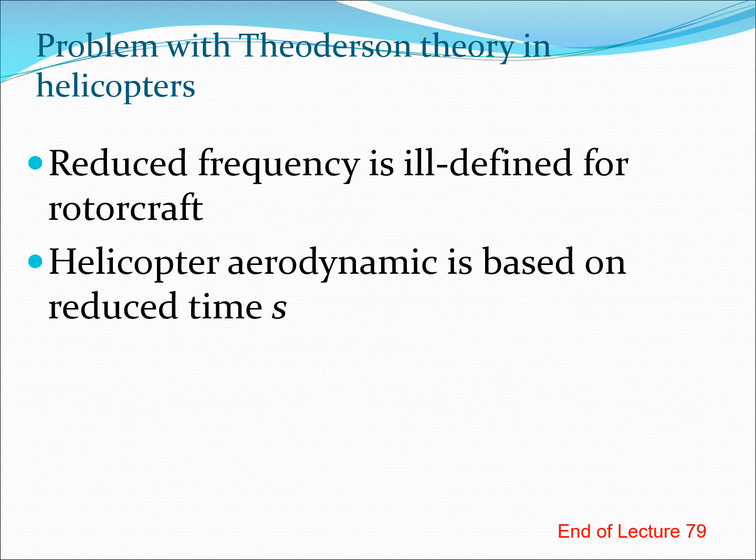But we also saw that the reduced frequency is ill-defined for rotorcraft because velocity is a function of both r and psi, and therefore one of the ways to use reduced frequency is for some qualitative work, whether you are trying to figure out the degree of unsteadiness and so on. But helicopter aerodynamics is typically based on reduced time s, and there are a whole bunch of algorithms or methods which have been developed using Duhamel's integral, Jones approximation, and so on.